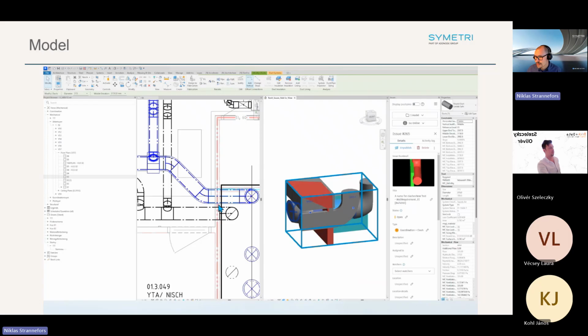When you're working with ArchiCAD, for instance, with IFC, we can do the same thing, but especially when we're talking about clash detection and more technical things, whether they're using Solibri, BIMsite, Navisworks, you name it, what they're going to produce is what's called a BCF, a BIM Collaboration Format, that third-party applications can read.